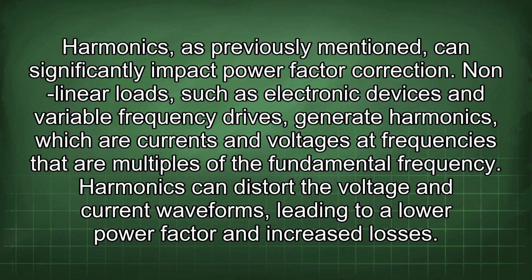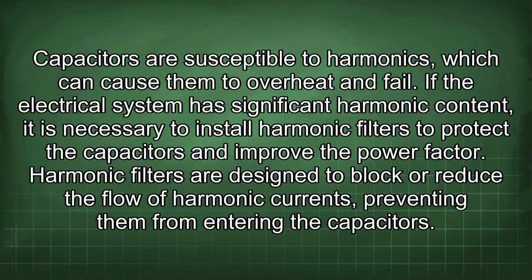Harmonics, as previously mentioned, can significantly impact power factor correction. Nonlinear loads, such as electronic devices and variable frequency drives, generate harmonics, which are currents and voltages at frequencies that are multiples of the fundamental frequency. Harmonics can distort the voltage and current waveforms, leading to a lower power factor and increased losses. Capacitors are susceptible to harmonics, which can cause them to overheat and fail.